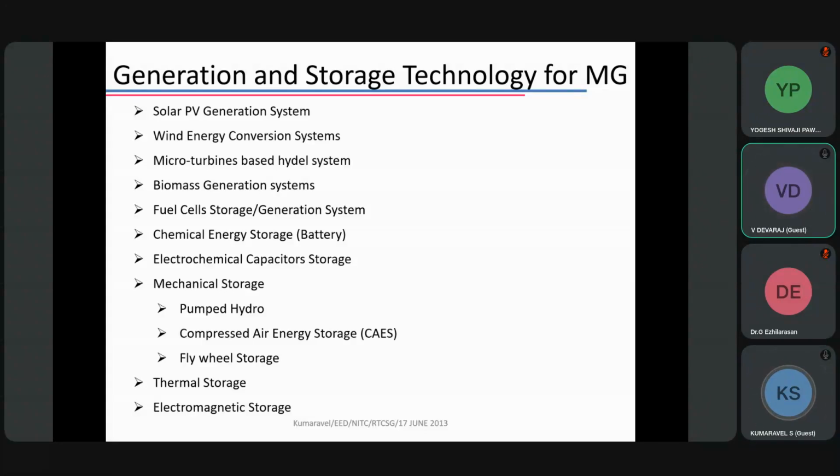For example, you are telling 1 kilowatt at 100 volt. 1 kilowatt at 100 volt, the current rating is 10 ampere. What is the meaning of these parameters? 100 volt in steady state, 1 kilowatt in steady state. It is not about the transient power. While designing, you will consider the peak power into the picture because you have to start the motor with a maximum torque, a peak higher torque to overcome the inertia.